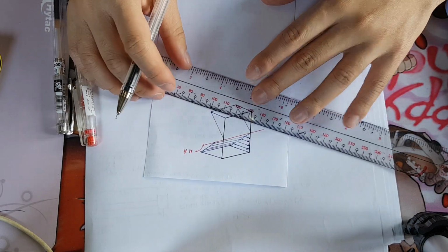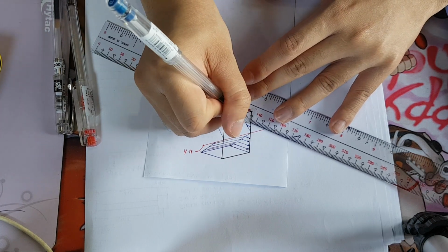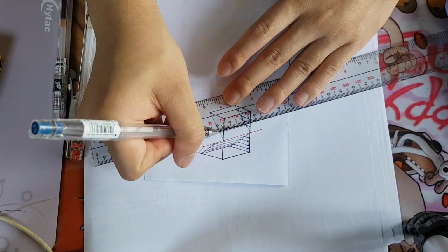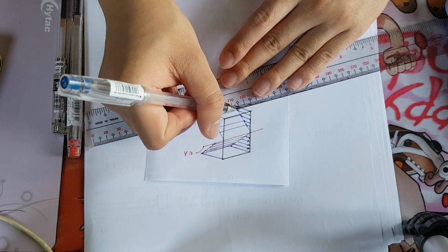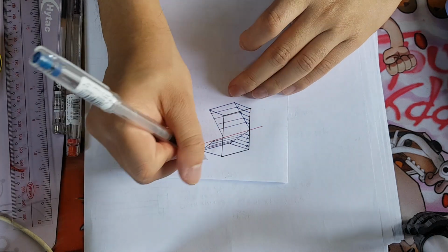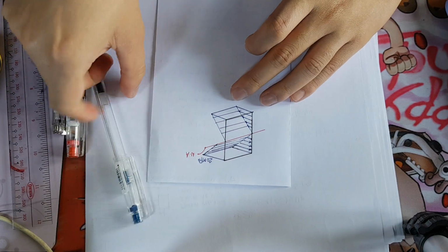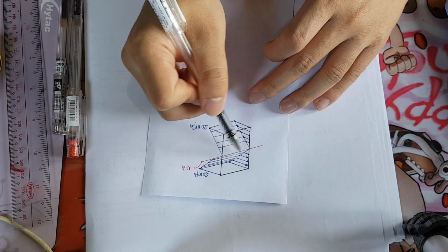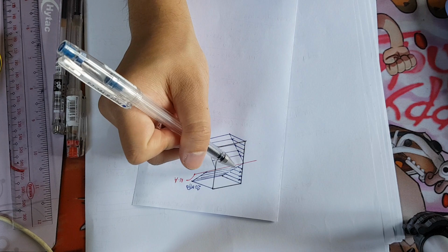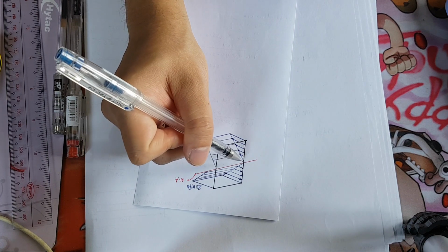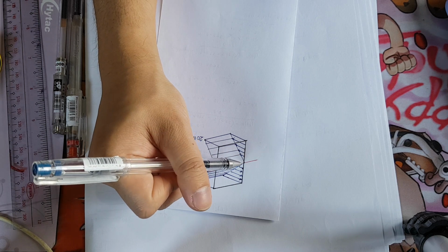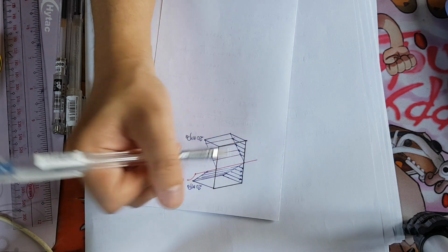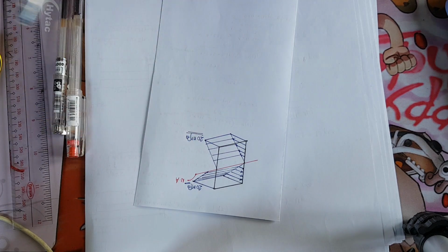Okay, so it is tension. It is going away from the cross-sectional area. So this is how our diagram would look like. So this is 20 megapascals compression, and this is also 20 megapascals in tension. If you're going to see, it is a linear relationship wherein as we go nearer the neutral axis, the stress is becoming lesser. As we go far away from our neutral axis, our stress is increasing up to the point of the farthest fiber from the neutral axis. Then there we can get our maximum bending stress.